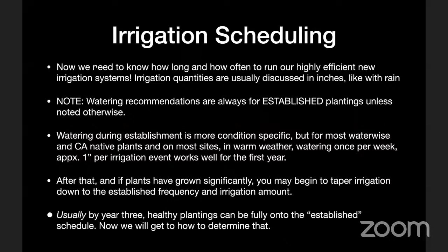And that irrigation once a week in general is going to be somewhere between 0.5 inch to 1 inch of water the first year. If in doubt, you can go with 1 inch of water per week through the first year to the landscape area for a new landscape. That's generally what I do when I need to kind of get a landscape going and kind of walk away. But sometimes you can get away with a little less water than that.